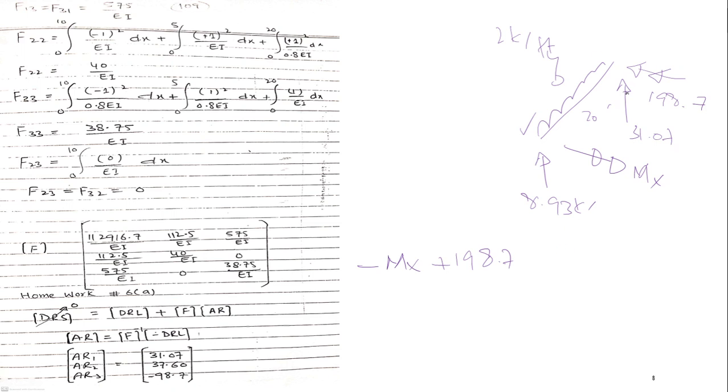Okay, this is y and this member is in z, so it would also form a moment anti-clockwise, minus 31.07 into 20. And finally, the upward load is forming a clockwise moment. You don't need a resistive concept here. You can follow a resistive concept here, but there's no need. It's so simple, 2 into 20 into 10. And when you calculate, you will find mx.